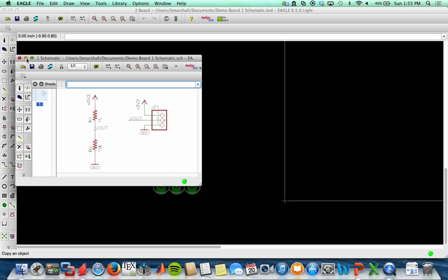So first things first, we don't have this many components, so we're going to go ahead and use the move tool, and I'm actually going to move the dimensions in here. You can see on the top left up here, it gives you the grid size. You can adjust that if you want. I'll leave that for now, and I'm going to make this board 1/2 inch by 1/2 inch. So I'll place it there, slide this in, feel free to zoom in, put it there,